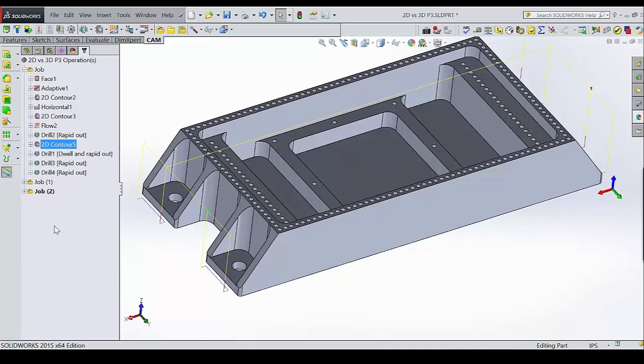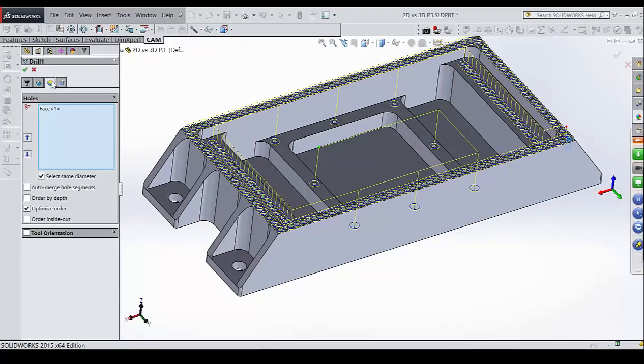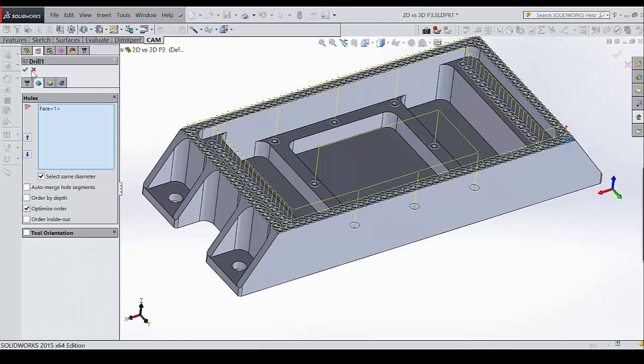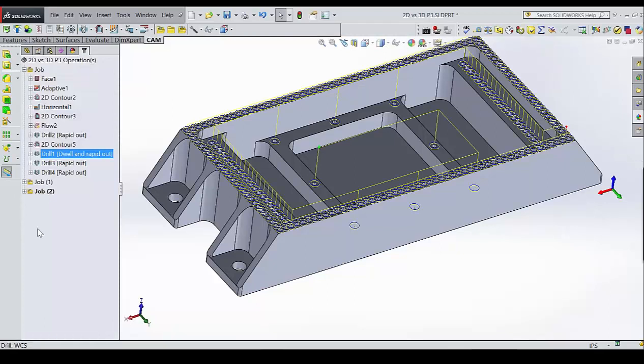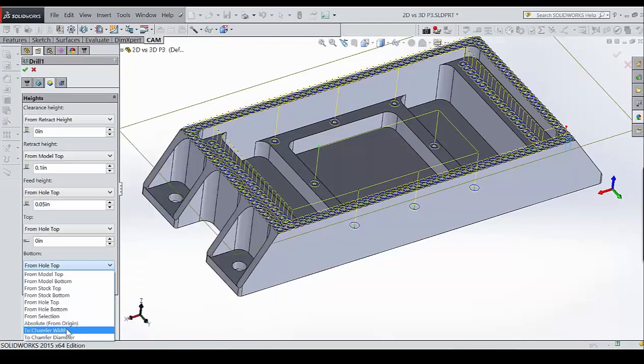Brian's coming in. So, to chamfer width, enter desired value, no model chamfer needed. Brian, maybe give us a little more context there. I'm not fully understanding the question, but I think it's related to whether or not we're entering a chamfer width on that. Instead of 0.288 diameter, click to chamfer width and enter 0.018. So I think he's actually helping us work through this rather than asking a question. Yeah, it's giving you an option to just put a chamfer width. So right there, I just changed over. So you would do chamfer width, right?